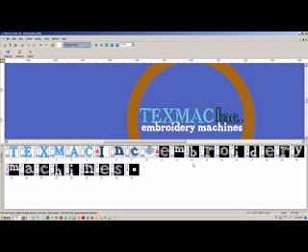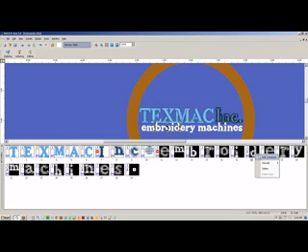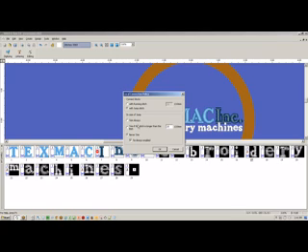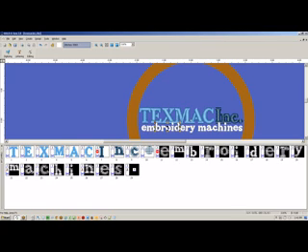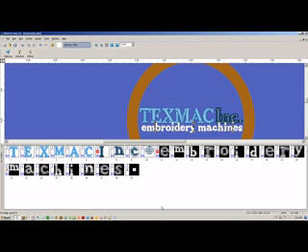One thing I forgot to mention too is you can also go in and look and see if you want to trim between some of these sections. Like you can see that with our tighter tolerances, this one there is a trim here. Maybe we want to remove that trim. Never trim there. So you can see where it is going to cut. Edit connection, trim here, or don't trim. Generally, you kind of don't want to trim. We definitely want to trim between embroidery and machines. You want to minimize the number of trims that you can, not only for saving time in sewing, but also you're trying to minimize the risk by not using the trimmer hardware.